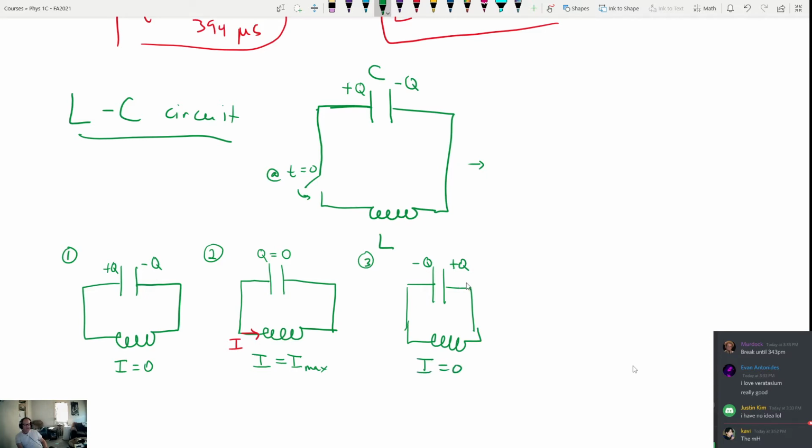Now what will happen is that this capacitor here is now fully charged up, and so it's going to drive charges back in the other direction to neutralize with this one right here, because after all, there's a connection here, right? So the next interesting step will be when the charge on our capacitor is back to 0, either side is charged, and there's now a current flowing back in the other direction here. So now the current is flowing this way and back this way.